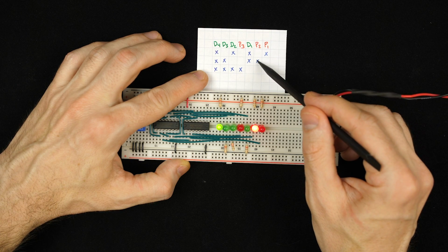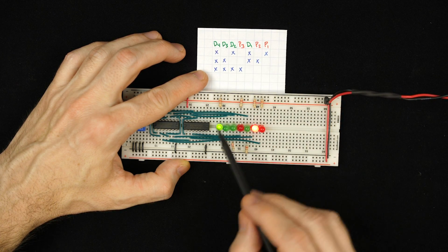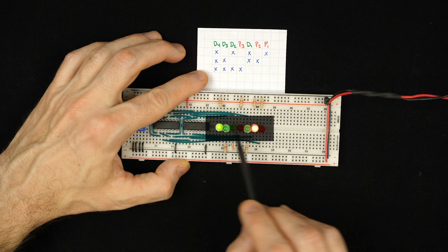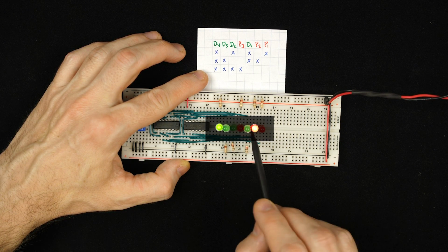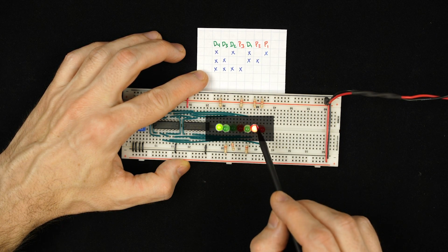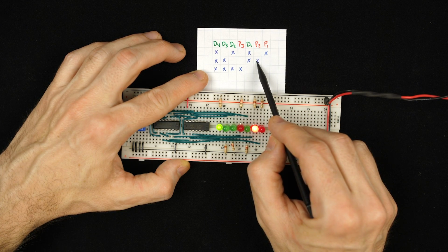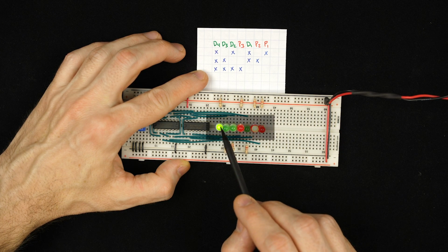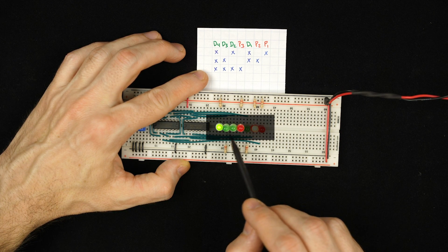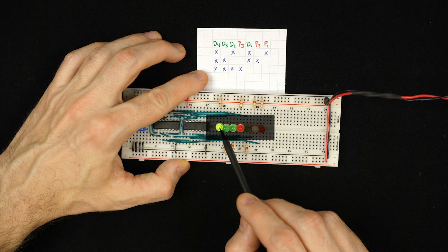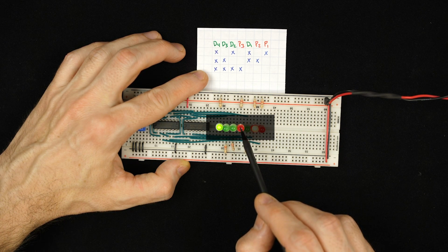But let's keep going. So parity bit 2 is on, but let's see if it's supposed to be. With parity bit 2, we're looking at these 2 bits as well as these 2 bits. That actually looks right, because we've got a 1, 0, 0, 1. And so we've actually got 2 1s within that group. So parity bit 2 should be on, and so that seems fine. But now let's look at parity bit 3. So parity bit 3 is these last 4 bits. So we have 1, 0, 0, 0. Well, that's wrong, because we only have a single 1 within that group, and a single 1 is not an even number, because 1 is odd. So that parity bit 3 is wrong.